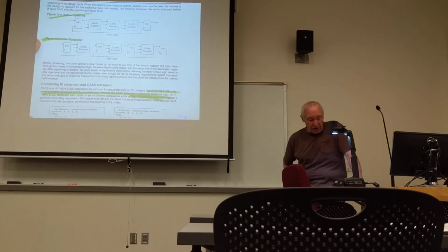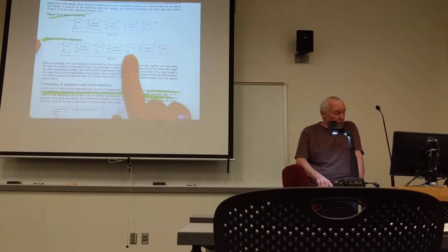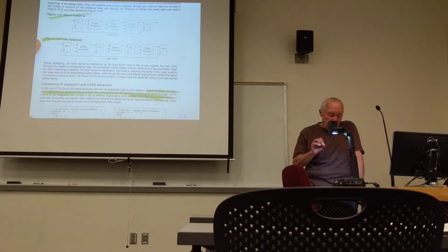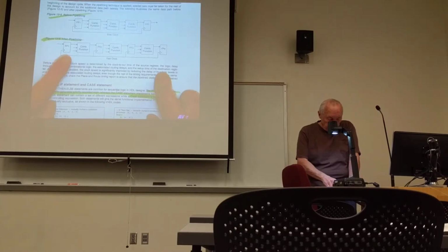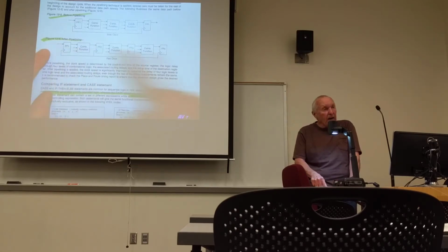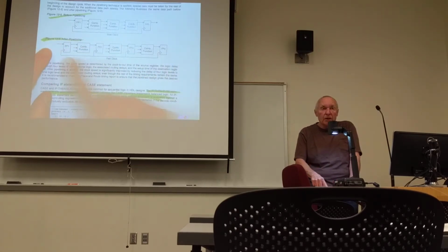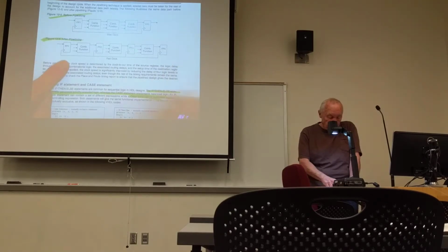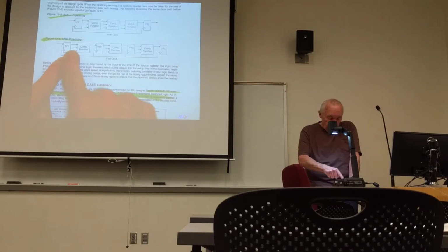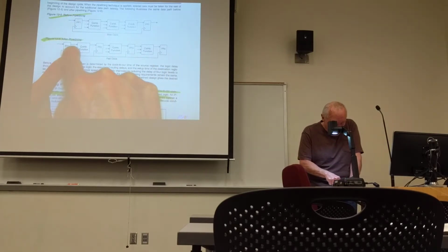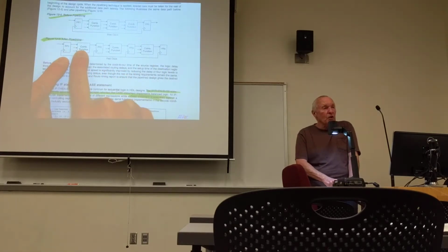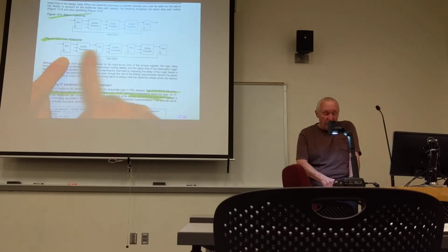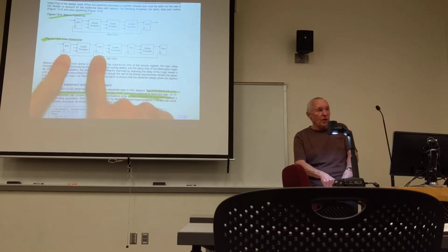And all pipelining means is I insert registers between the combinational logic blocks. The reason why the pipelining turns out giving you a faster design is, let's suppose I've got a number of data elements that I'm going to be running through this particular data path. So I apply the first data element. On the clock edge, it gets stored in that output. That combinational logic block can now work on it and provide it to the next register. Now you notice these two registers are clocked with the same clock.